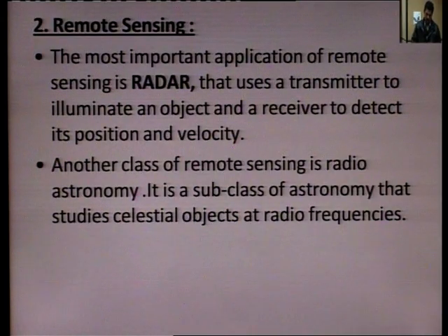In a radar system, high power microwaves are sent into free space, and if any object is present in space, the wave will reflect from that object. At the receiver end, the frequency may change due to the Doppler effect. So, that echo can be used to detect the position or velocity of an object.